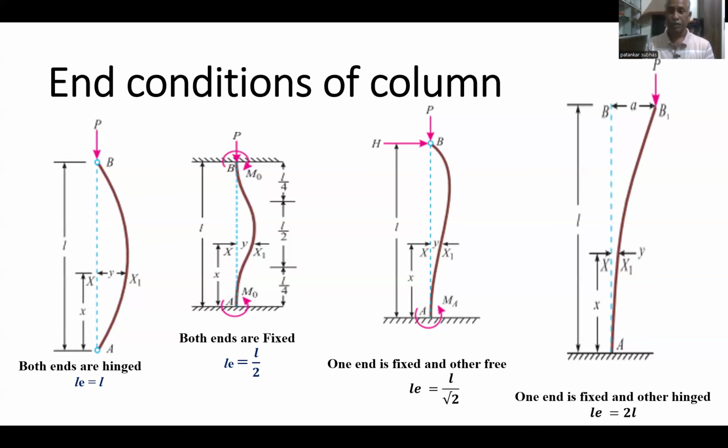Sometimes, for an electric pole, or a foundation without a beam, there is a column at the ground level or plinth level. In that case, it acts as the fourth condition: one end is fixed while the other is free, not hinged.